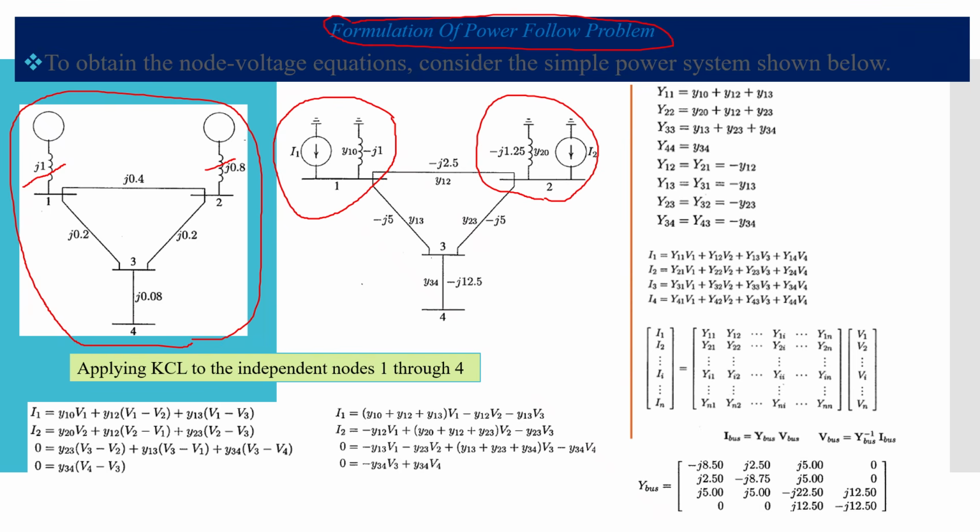So in order to perform the power flow analysis in terms of Y bus, we'll convert all impedance and the reactance of the transmission line to admittance. So for example, here we have one ohm reactance. When we take inverse of this and represent as admittance, we have minus J1. Again, for this transmission line, also we have impedance of 0.4. So when we take the inverse of this, it becomes minus 2.5 J, and we'll convert all the impedance into the admittance, and they will form the voltage current characteristic equations for that.